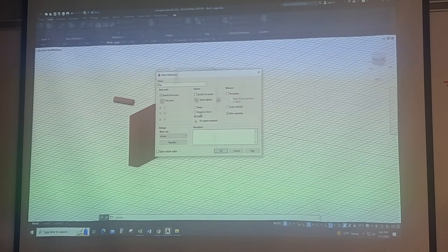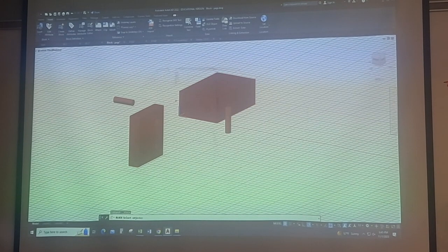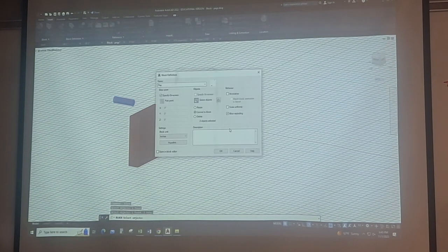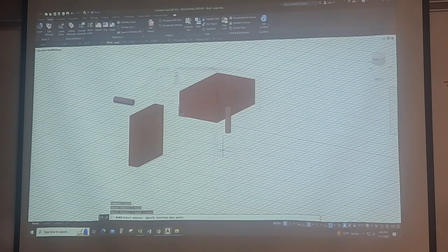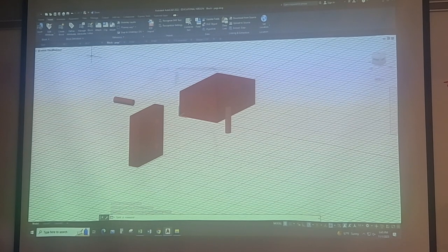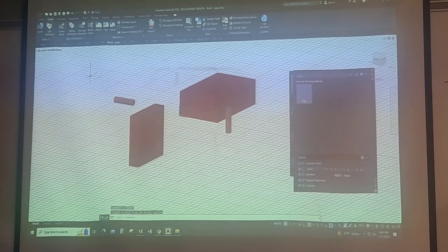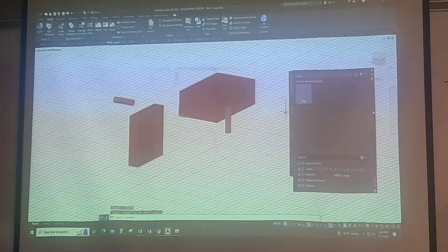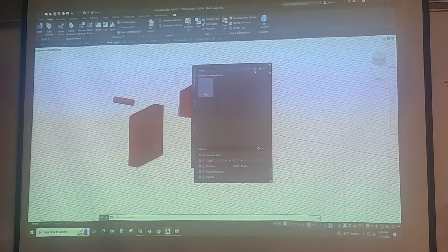I'm gonna go ahead and select the convert to block. And then I'm gonna come up here and pick the select objects button. And I'm gonna select these 2 pegs right here. I'm gonna tell it okay. That's where AutoCAD says, where's your base point? Because I told AutoCAD I wanted to specify it on screen. So I'm just gonna come up and pick a point at the bottom of this peg and everything's great. If I go into my insert command, you see insert down here, similar to that XREF that we did a moment ago. The alias is I. If I go I and spacebar, it's similar to that XREF dialog box that we had earlier.